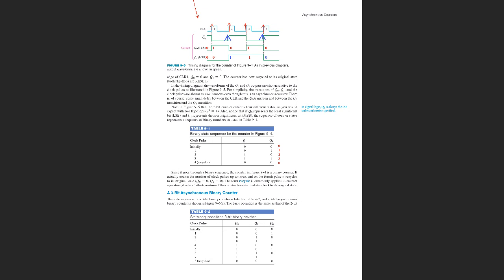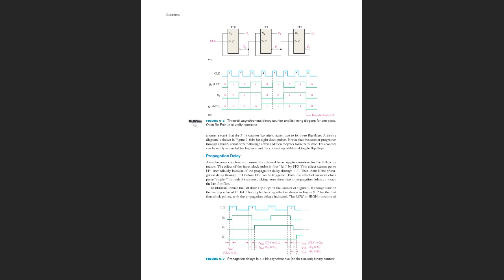We may connect 3 D flip-flops and have a 3-bit binary counter, in which flip-flops act on each other. One flip-flop is affecting another exactly the same way as the previous example has shown. So we have 3 D flip-flops, and the clock is connected to the first one.